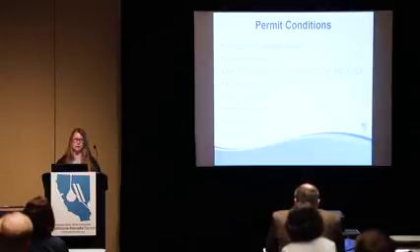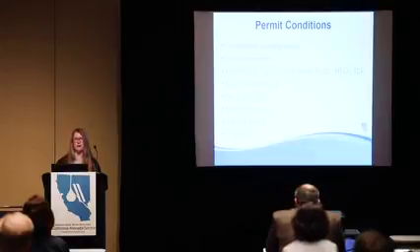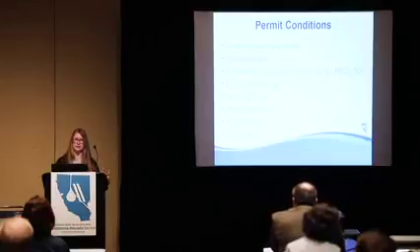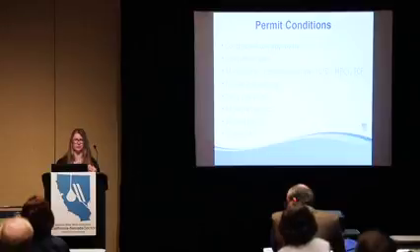One permit requirement is that we are to use virgin GAC. So there are plans this year within Cal Water to do some testing and to look at using a reactivated GAC material, which is where they take the GAC out from the vessel and the vendor takes it back and refires it, and it puts all new surfaces onto the GAC particles. So we are going to be looking at that this year.